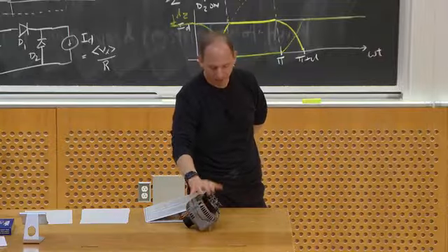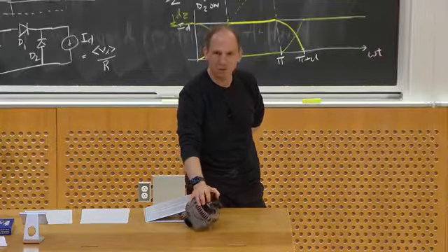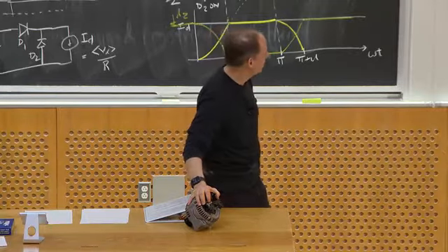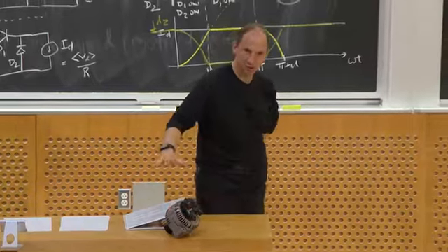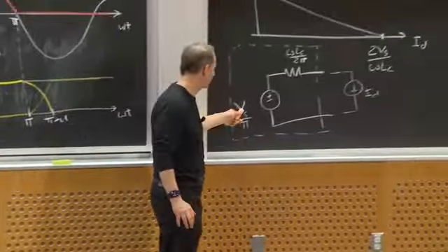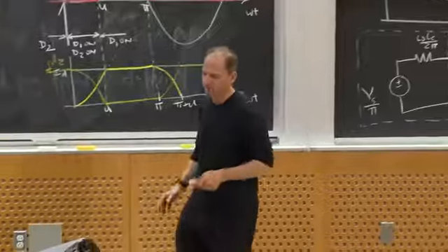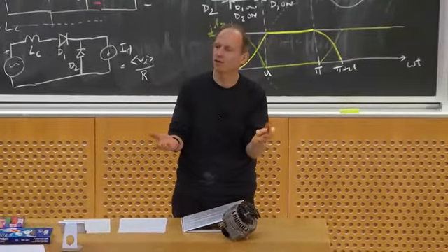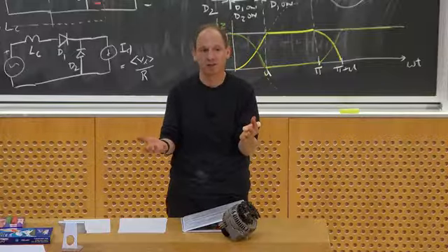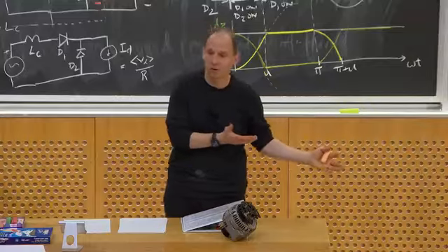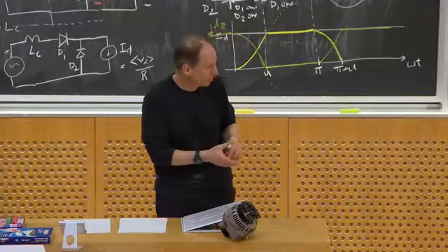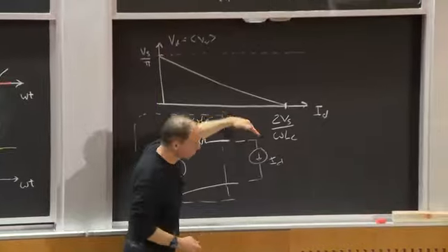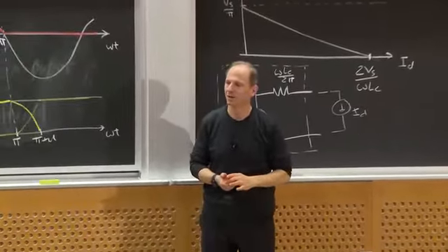Okay? So the output of this thing is supposed to charge basically a 14-volt automotive battery, right? How big do you think the effective AC voltage, this Vs, is to do that? Whereas you might think you wanted to synthesize a rectified voltage of like 14 volts, it doesn't. It's more like 70 or 80 volts when it's under full current load, all right? So that alternator is really generating a really big voltage with a really steep droop to it, okay?